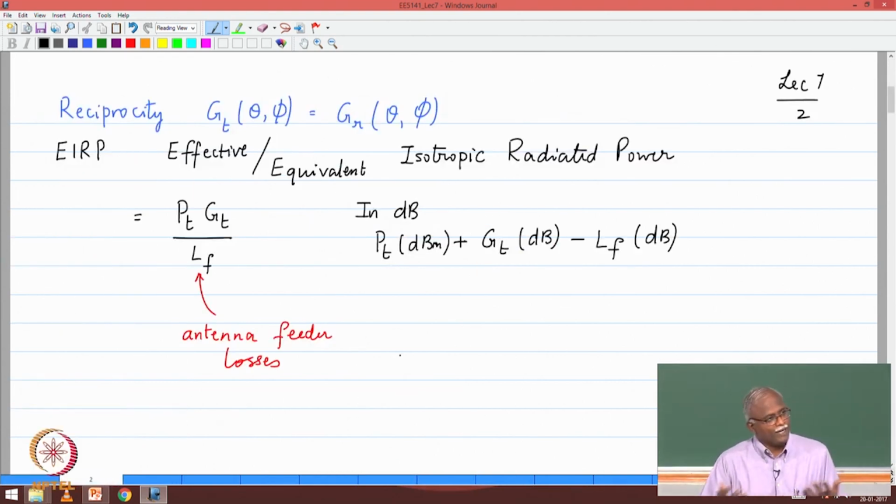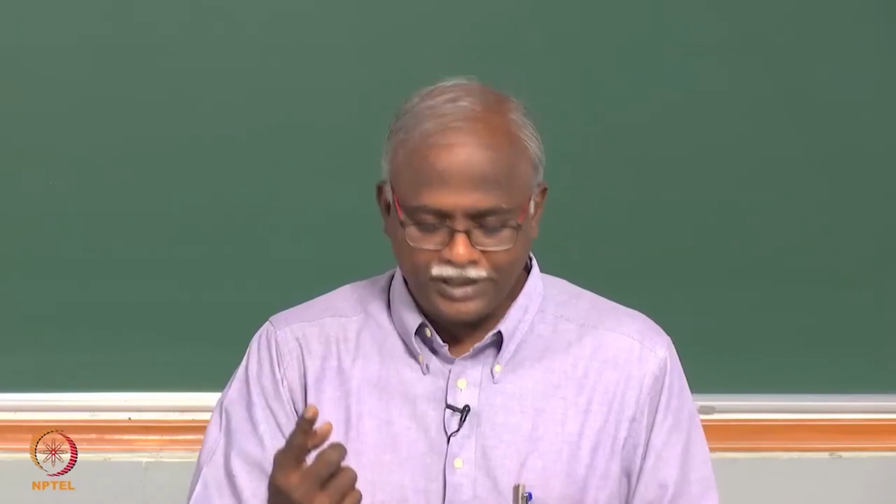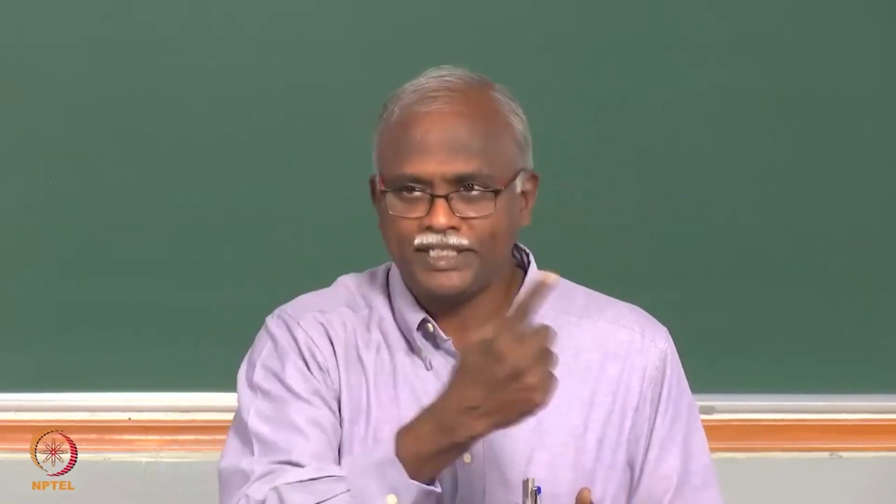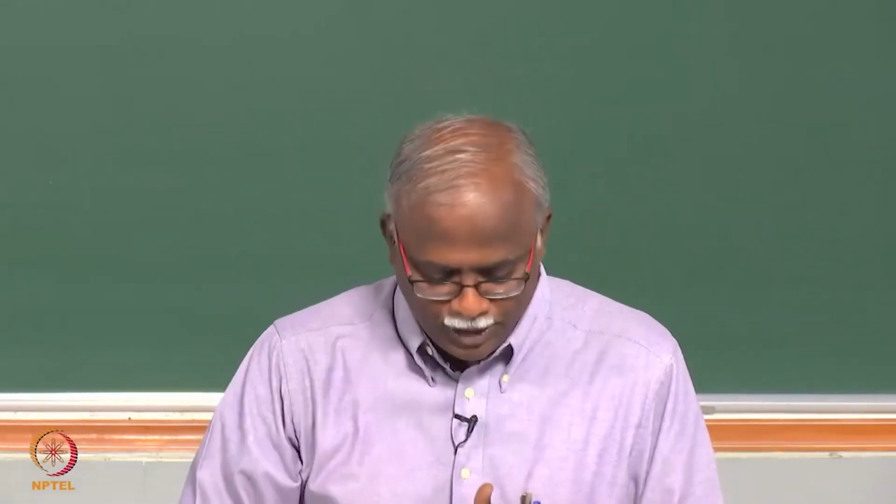We also made a few other observations, that typically an antenna would be characterized in terms of its elevation angle theta and the azimuthal angle phi. Transmit and receive gains are the same. We are also interested in the pattern of radiation. We typically have omnidirectional radiation for mobiles. This is different from isotropic, which radiates in all directions. Omnidirectional is omnidirectional in the azimuthal plane.